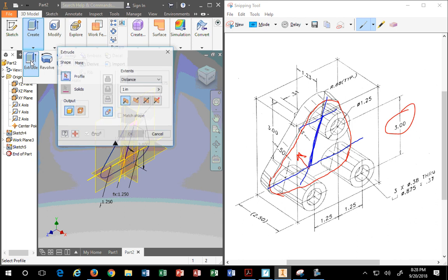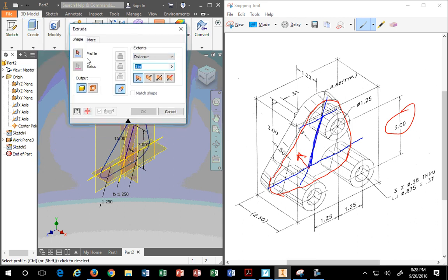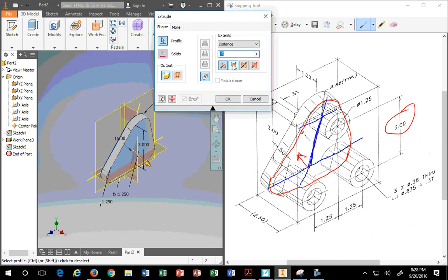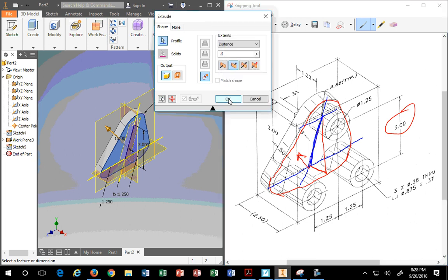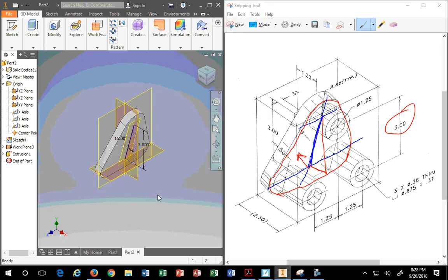So when you go to extrude, your 1/2-inch extrusion of this face is not forward. It is backwards. You have to extrude away. Otherwise you're going to mess up the front. This triangle is drawn in proportion to the front of this object. Okay? Not the back of it. So you have to extrude back. This is very important. That's how you get the correct sides.